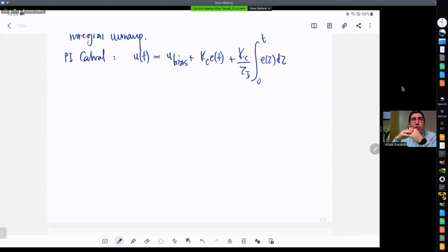For example, you have a motor which has a torque limit, and you need to apply a torque that is larger than the torque that the motor can apply. So the motor achieves its maximum torque, but it cannot go any further. If it cannot actually achieve the desired torque, the error will not diminish to zero anymore. You will have a constant error that's not going away. So the integral term will keep accumulating that error and will accumulate a large sum as part of the integral term.